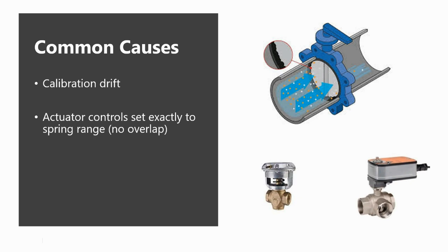For electric DDC actuators, you want about 1/2 to a full volt of overlap above and below the span of the voltage that's needed to drive the valve between fully open and fully closed. Then for pneumatic systems, since most pneumatic controls are getting pretty old and sloppy these days, I recommend at least 1 full PSI of overlap as being even better to help prevent leak by.